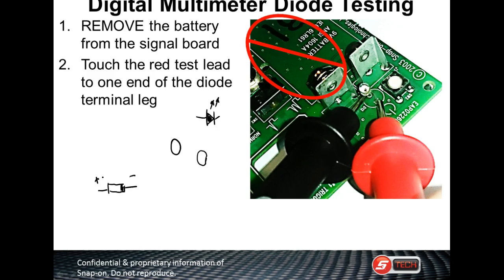So what we're trying to show you is it really doesn't make any difference how big the diode is. You can check it with your meter on the diode scale. Are we okay? A lot of people think you can't check these, but you sure can. But you always should do what? If it checks good one way, always check the other direction, just to make sure the thing's not leaking.